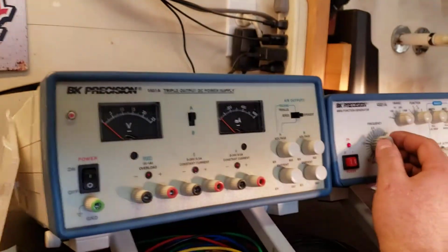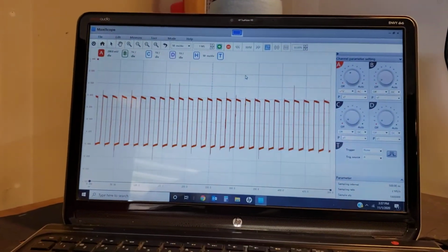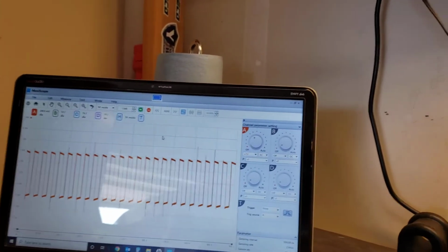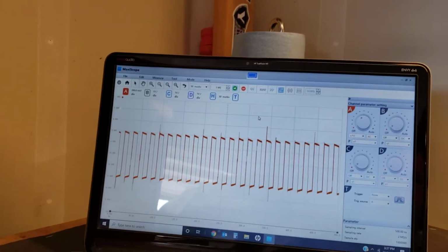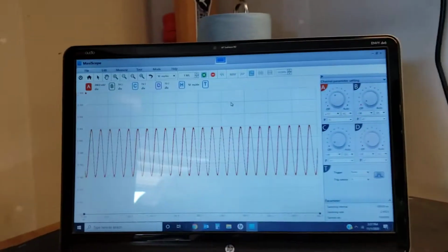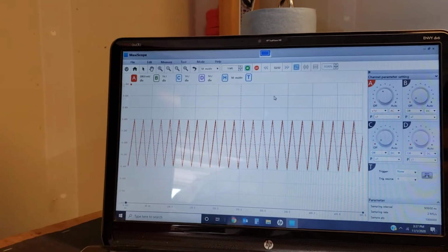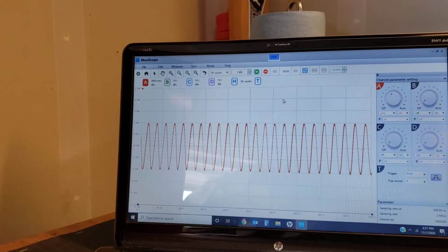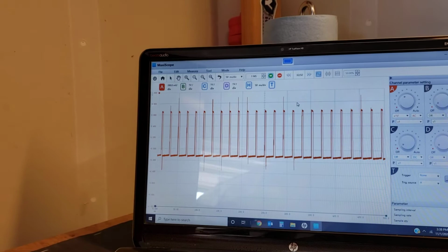And all I'm doing is this button here for frequency and hertz. So that's something like we had there earlier, plus minus 400 for amplitude and whatever that frequency is, which you can measure out, but I'm not really concerned right now. But just to show you, if you change this function button here, I just moved it to a sine wave, and you can see the sine wave. You can do a triangle wave, or you can go back to square, which is right there. There's another type of square wave there.